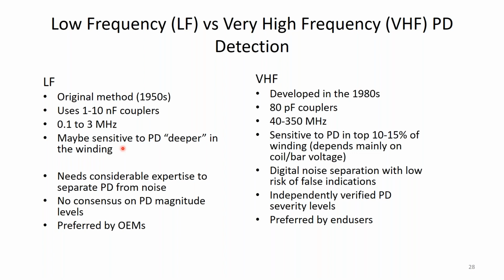So there's a little bit of question still about that, but in the low frequency range, you have to be very careful about which frequency you use because you can get a lot of attenuation, because it's not just simple inductors. There's series inductance in the slot, series inductance in the winding, capacitance between coils in the winding, capacitance to ground, and lots of mutual inductances. It's a very complex network, and there's lots of notch filtering or resonances and anti-resonances going on. So the frequency is very important.